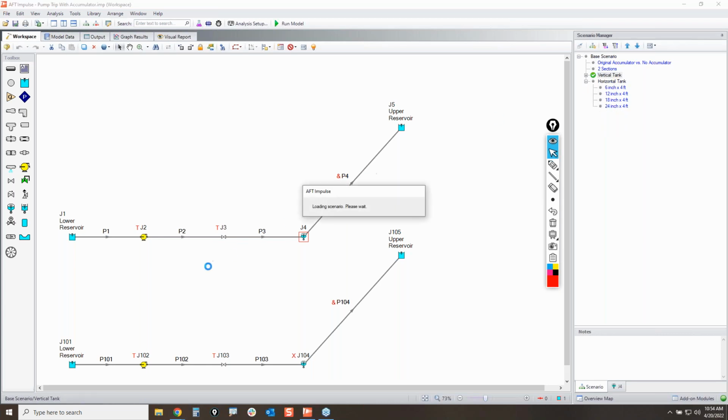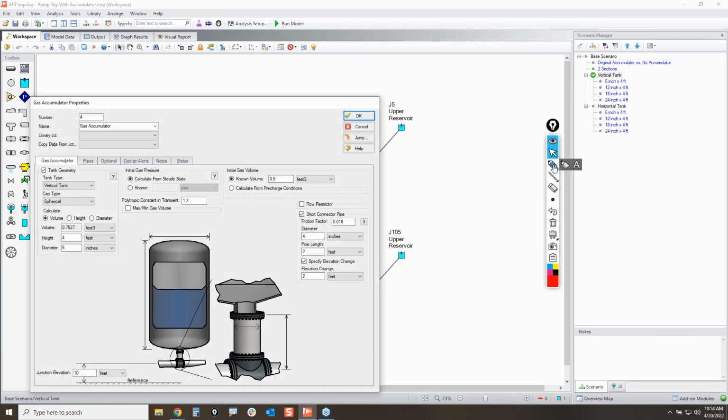The reason why I keep clicking cancel is because one of my biggest tips that I always recommend is if you are doing anything in a window that you're not intentionally actually changing, never click OK, because you might accidentally accept changes that you didn't intend. So even if you're just going in here to look at something, when you leave that window, click the cancel button just to prevent any accidental changes. So a little tip there.